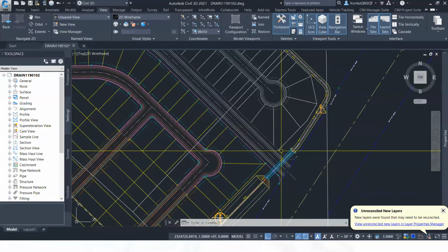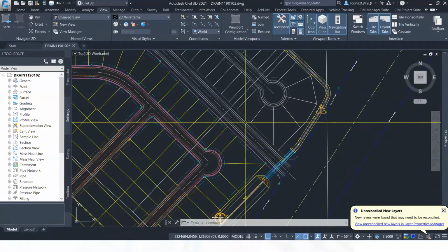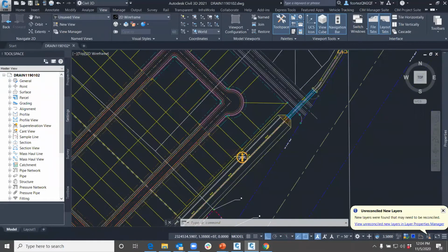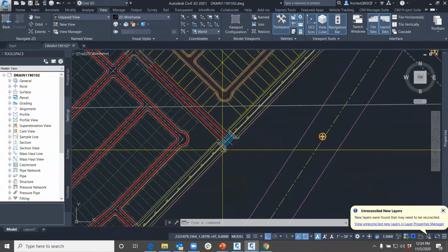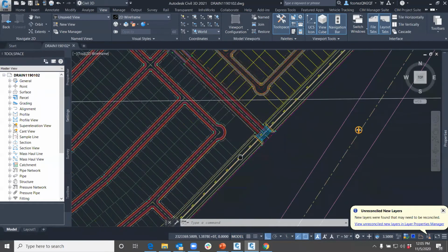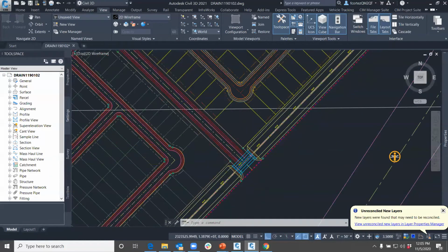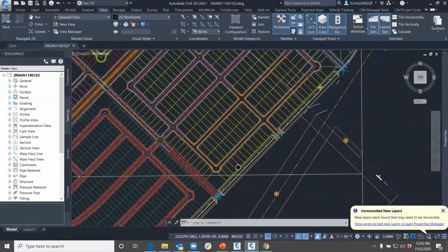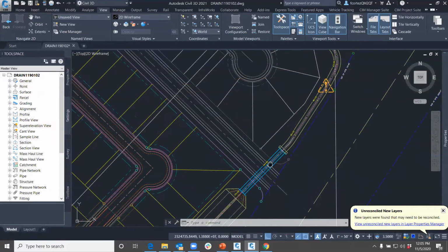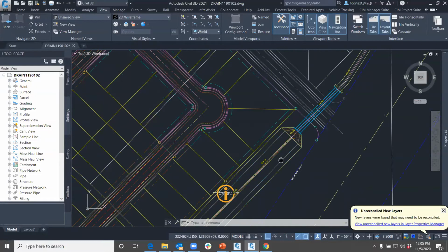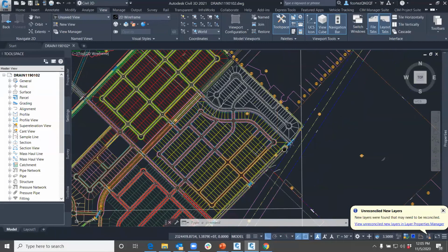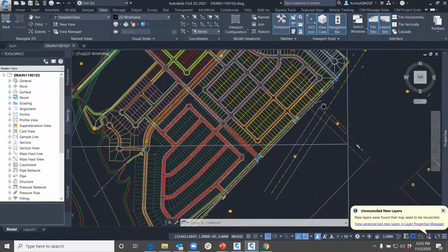What I'm going to do first is come into Civil 3D. So we will see this is a subdivision. And if I look along this edge, you can see there's a variable width channel here. This channel is pretty wide here. This is a slightly smaller channel. And as we get up towards the top, the channel is really small just because of the drainage area, and we're at the top of a hill. So in a typical workflow, I might have 4 different subassemblies for this particular channel.